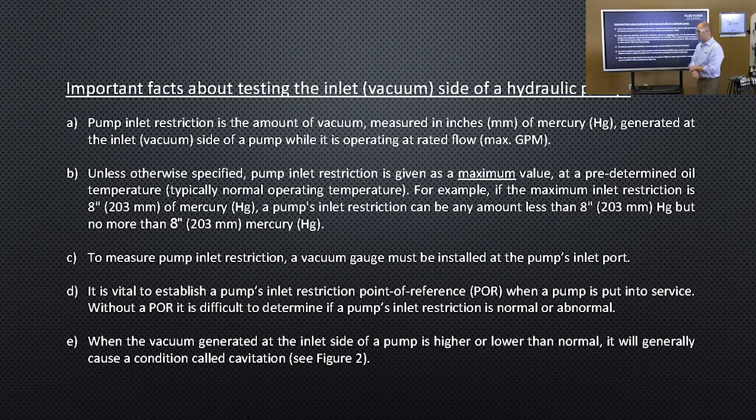D, it is vital to establish a pump's inlet restriction point of reference when a pump is put into service. Without a point of reference, it is difficult to determine if a pump's inlet restriction is normal or abnormal. So bear in mind that over 99% of hydraulic pumps operating in service today have no means for maintenance people to non-invasively check inlet restriction. It's not possible.